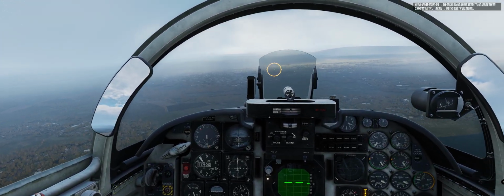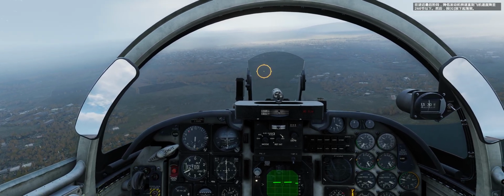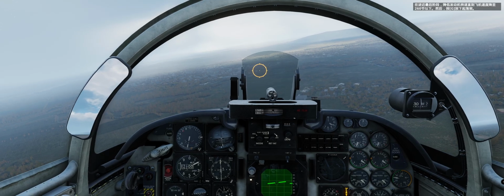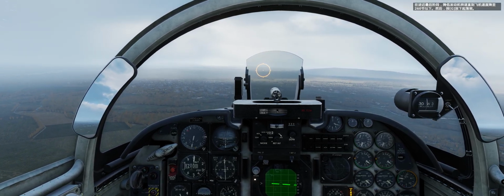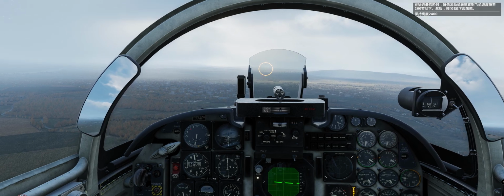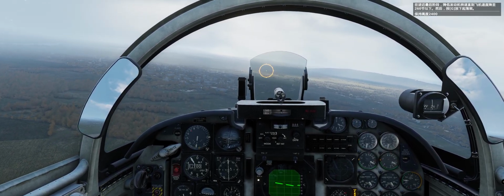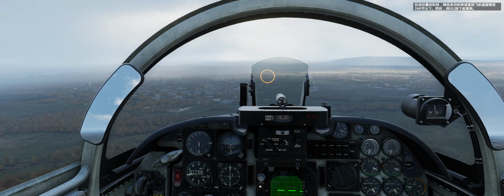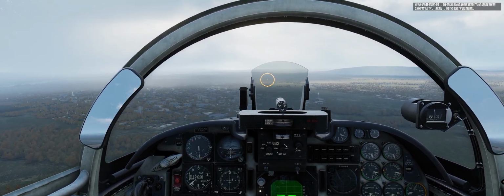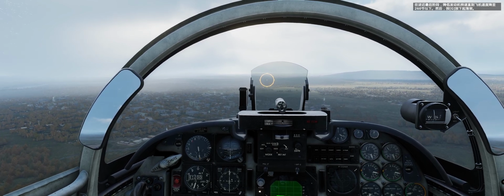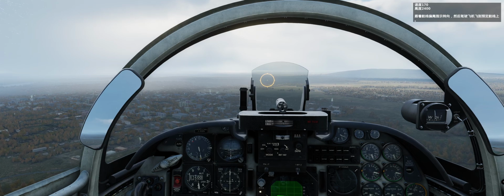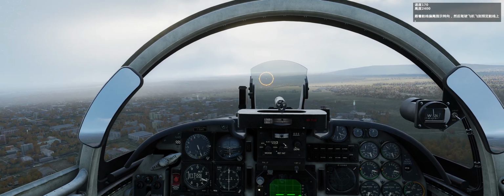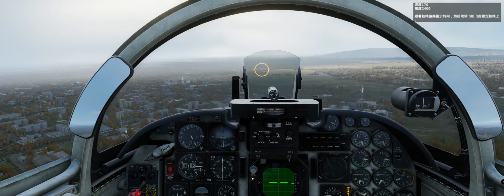When you are on final approach, reduce engine RPM until your airspeed is less than 260 knots, then extend the landing gear by pressing the G key. Speed is 170. Altitude is 2,400. Turn towards the deviation bar to maneuver the aircraft on the desired course.